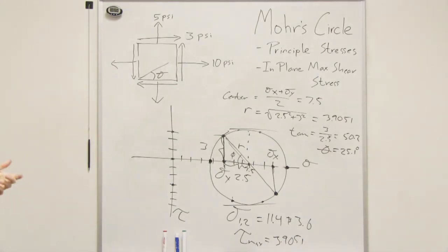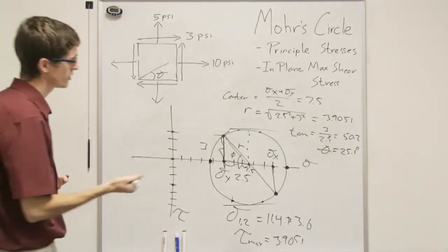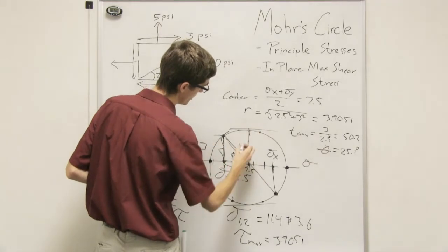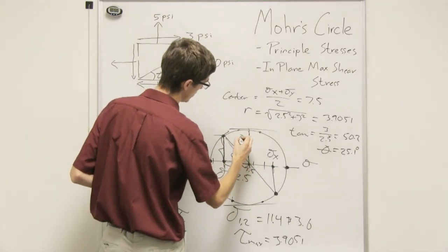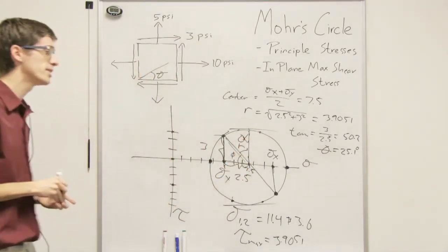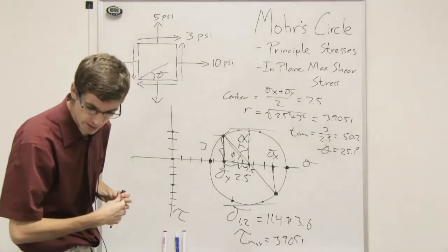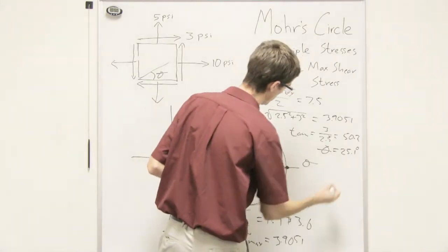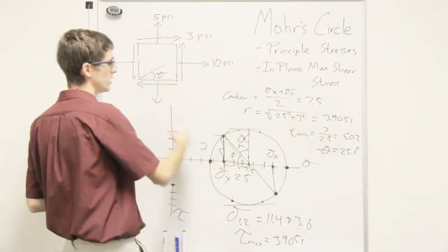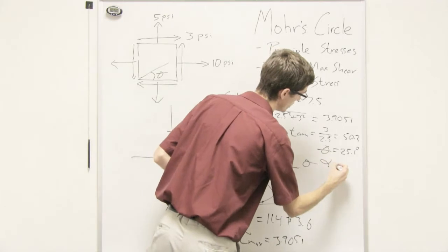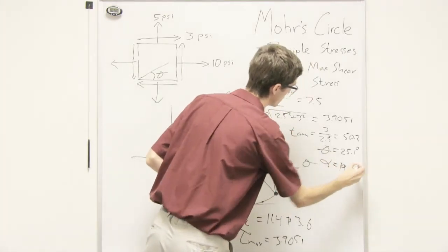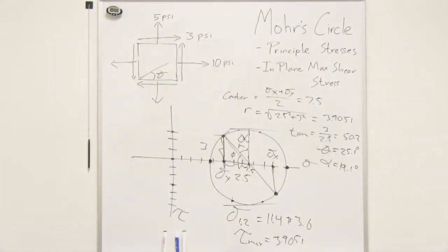Now we do the same type of thing with finding the shear stress. We just rotate the other direction, and we're going to call this angle, I don't know, alpha. We do it the same way: the opposite over the adjacent, take the tangent of it and divide it by 2, and that'll give us alpha, which we find to be 19.1 degrees. Cool. Well, that's pretty simple.